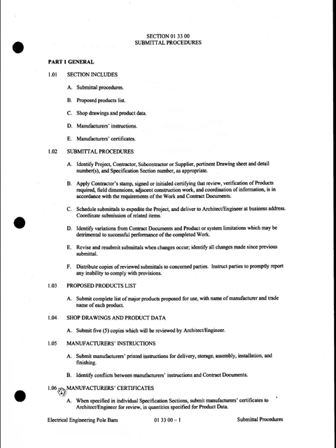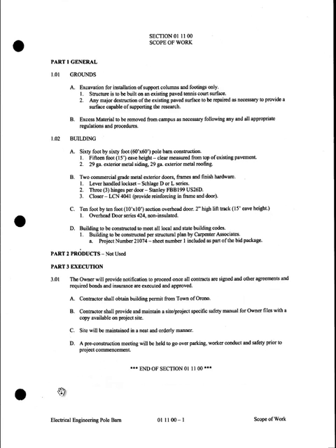So you can see my specifications are actually just the scope of the work. That's all we got in there. It's a pretty basic building. And these specifications, you'll notice, this is easy to show because it's on one page. A specification consists of 3 parts. Below the title, we have general information, the products, and the execution.